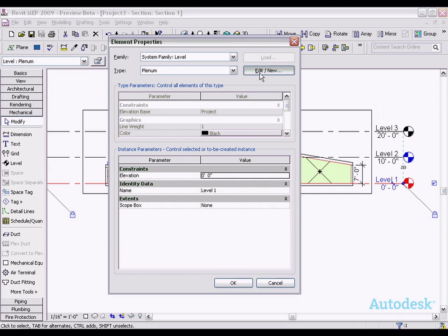If we look at the actual space itself that's been defined, we can see here that the roof is actually cutting in, and this is the example we saw previously where the roof itself is actually down here below the cut plane, which is why we're seeing the roof showing up in this particular view. But what we see here when we select this space is the actual cross-section of the room. And in this case it's fairly simple to understand what's defining that cross-section. It's these bounding walls that exist on the extents.